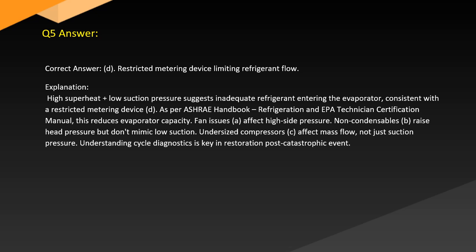Fan issues, A, affect high side pressure. Non-condensables, B, raise head pressure but don't mimic suction. Undersized compressors, C, affect mass flow, not just suction pressure. Understanding cycle diagnostics is key in restoration post-catastrophic event.